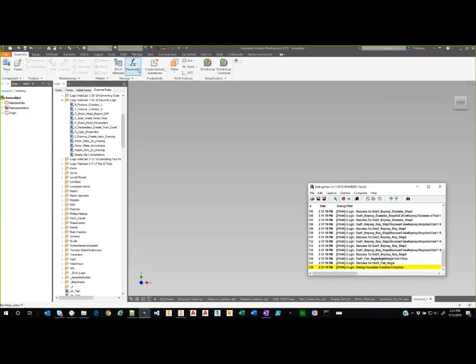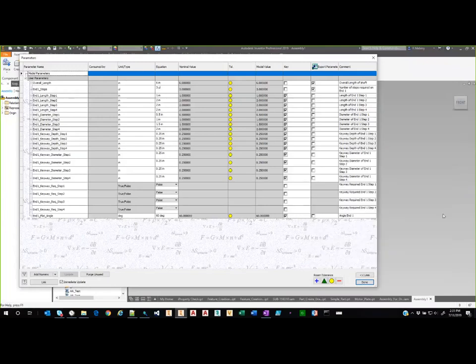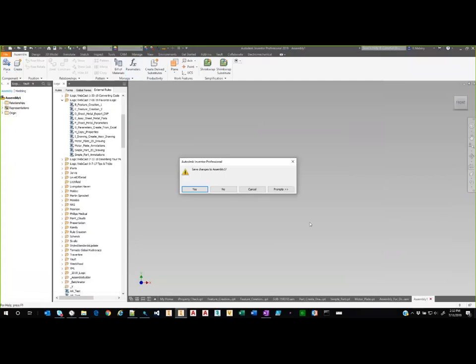So if I open up my parameters dialog box, right, there's all those parameters. They've got the unit types as I set them, all the values as I set them, the comments are there, etc. Again, it saves me a lot of time at the offset of a project where I know what certain parameters are going to end up being. I can keep them in order. I can quickly create them. Okay, doesn't have to be an assembly. Again, that can be from in a part file as well. Okay. So let me close that guy.